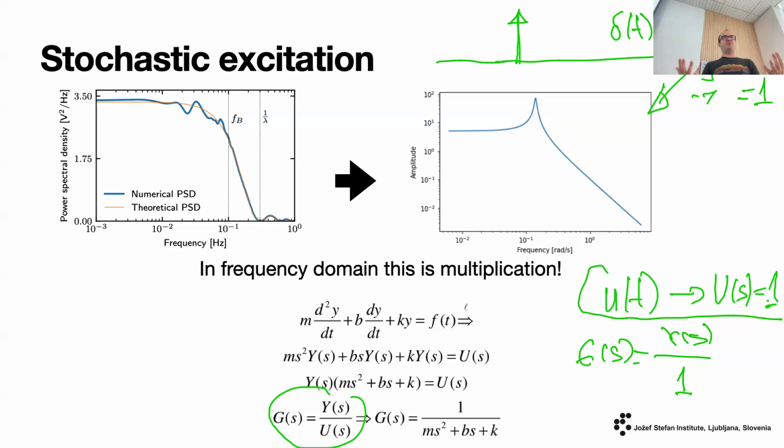So if we can generate such a signal, in reality, we don't need EIS. We can just come and kick a system, and the output will be its transfer function. And that's why a lot of mechanical engineers, when they do testing, they hit stuff. When you hit it, it starts to ring out. The frequencies that it rings out at are the poles of the system.